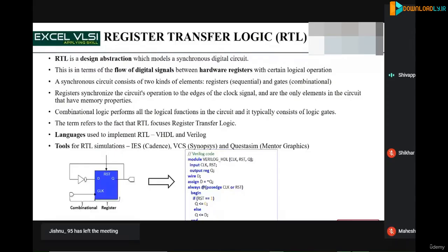Within the always block, you have written at the passage of the clock. Anytime the clock changes or reset changes, you go in, and this is procedural. The always and assign are concurrent. Concurrent means this and this whole thing will be executing at the same time, but within the always block it is procedural, meaning one after the other.